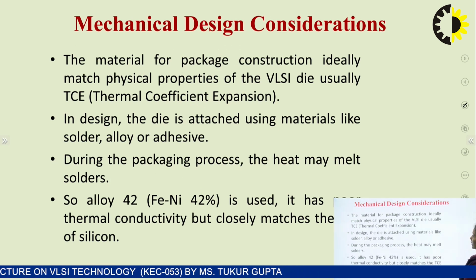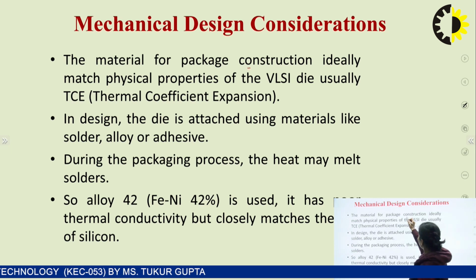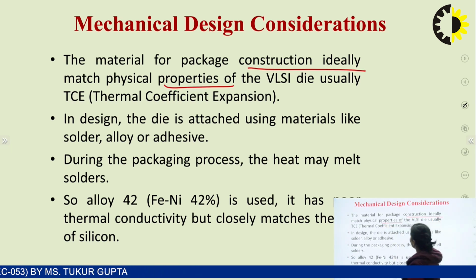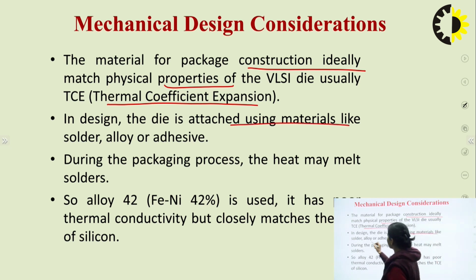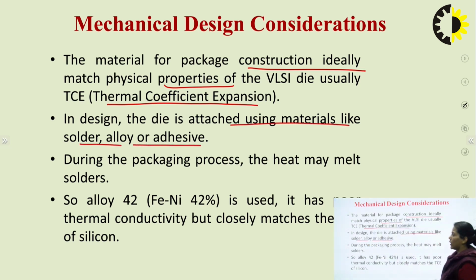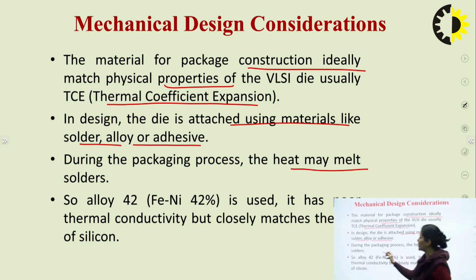When talking about the mechanical design considerations, the material for package construction should ideally match physical properties of the VLSI die. That is the thermal coefficient of expansion. This very particular property should be matched. This is because the die is attached using the materials like solder, alloy or adhesive, and during the packaging process the heat may melt the solders. So we have to make use of such substances, such components, so that the thermal coefficient of expansion is matchable.